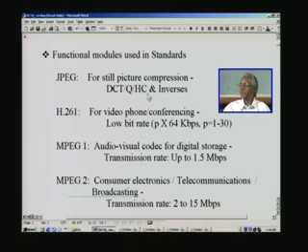Naturally this will be at the encoder stage, wherein you take a raw image and compress it by using these techniques and then send it over a channel, and at the receiving end, which is called the decoder, we have to do inverse operations of this. For example, VLD will have to be applied first, followed by inverse quantization and followed by inverse DCT.